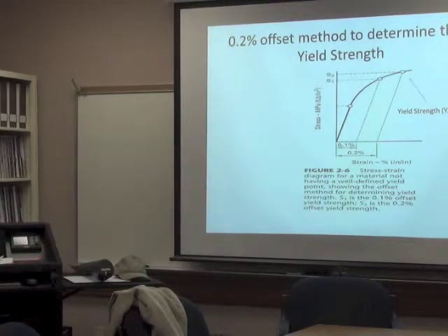If you see the stresses are too large, beyond the safety factor, then one thing you can do is select another material with better strength properties, or design your sections bigger, or put rounded corners on there instead of sharp corners, and reduce the stresses.